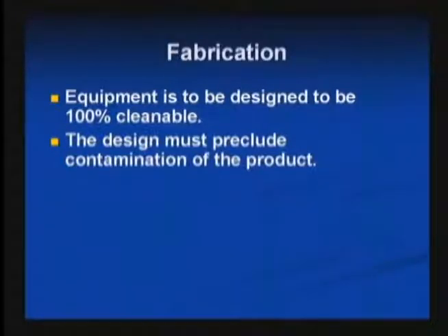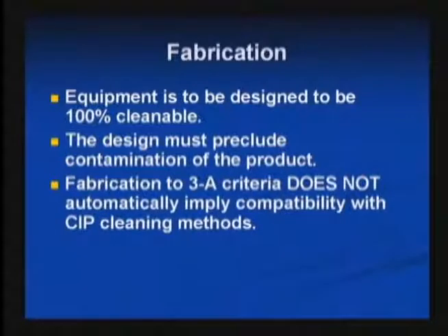As we've said a couple times already, fabrication to 3A criteria does not automatically imply compatibility with CIP. You can make either a manually cleaned item or a CIP cleaned item under the same standard. It covers both possibilities.